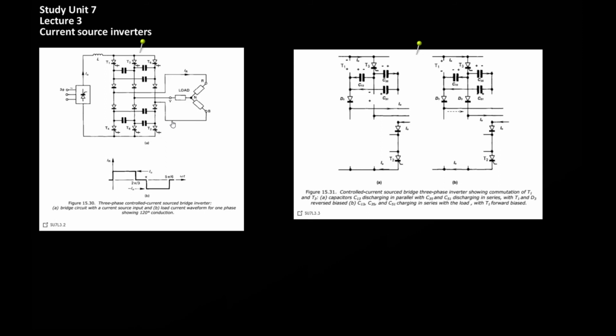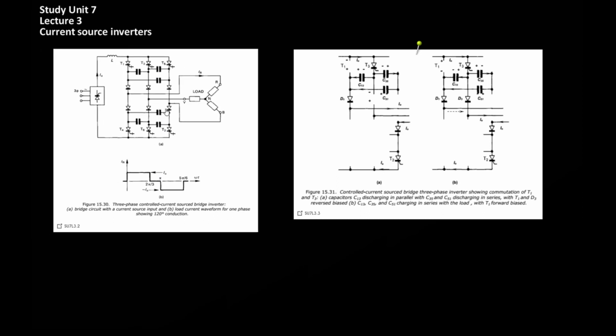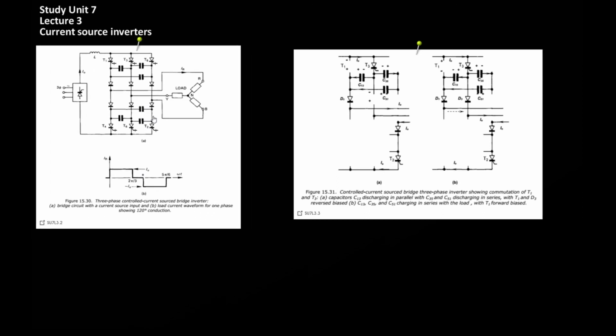Just as with the voltage source inverters, pulse width modulation can be used to control the switching intervals of each of the active devices in the converter network. By applying PWM techniques, it is possible to build very high voltage, high energy converters which still have very good harmonic performance and thus better power delivery to the load.